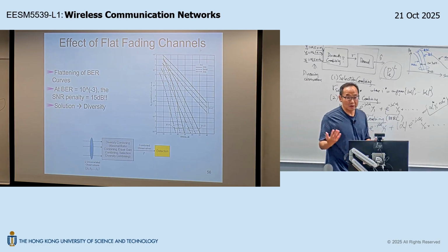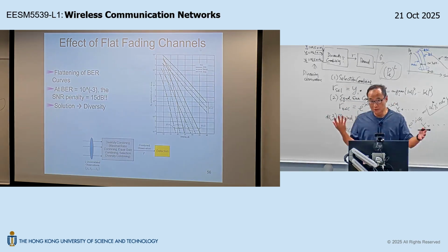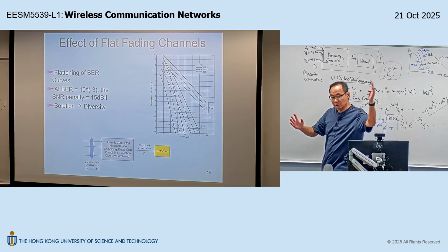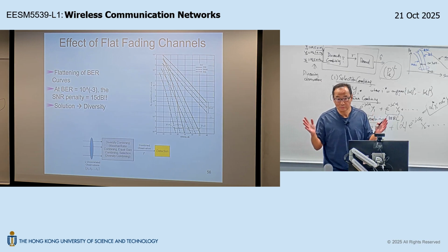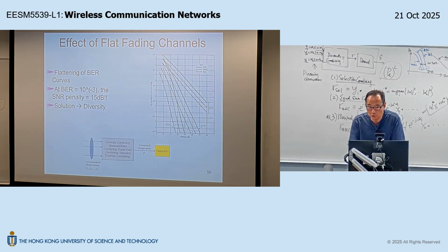You figure out the reason that the access points in the market have this limited coverage is because of fading, because of this flat fading, right? Because of this flat fading, the trouble is the error probability falls off slowly, let's say like this. So if you want to achieve a certain target error probability, let's say 10 to the power minus 4 for your data application, you need this amount of signal-to-noise ratio, which is pretty high, 40 dB. With 40 dB, that means the maximum path loss between the transmitter and the receiver would be very small. And that translates to a few hundred meters of coverage. Is that okay? That was a problem. So how do you extend the coverage of your solution?